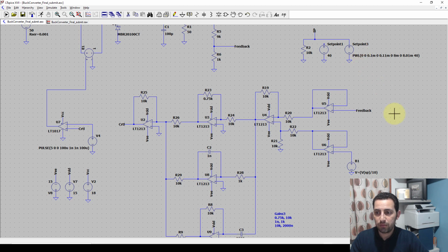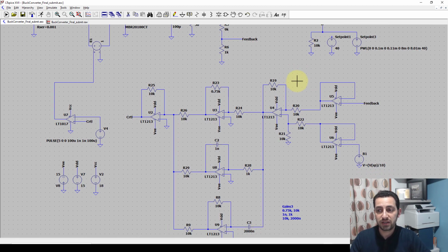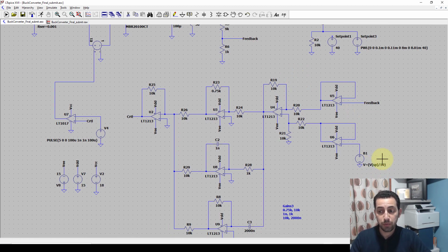And this set point now is transferred to this operation, so this supply here, as just another equation here, but without 5, okay? And this is a buffer. So this buffer and that buffer are just to transfer the value of the set point or the feedback to these points. And this block here is the subtractor. As you remember, in a feedback system, we subtract the feedback from the set point here. And after the subtractor here, we have the error signal. So this point here is the error signal.